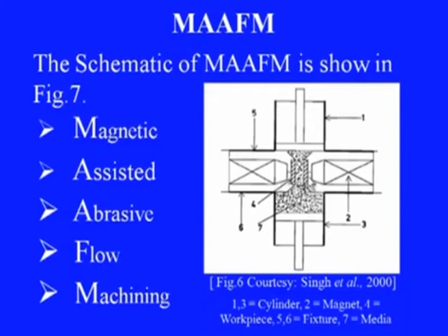In between, however, the workpiece surfaces are there, and thereby this will cause abrasion with a better impact on this workpiece surface, which will result in enhanced material removal as well as enhanced surface finish. The magnetic field increased the resultant cutting force on this surface because of the change in the incidence angle with which the particles impinge upon the surface.